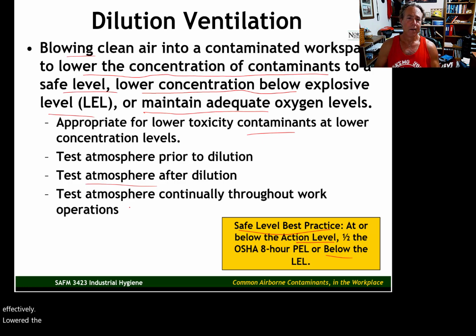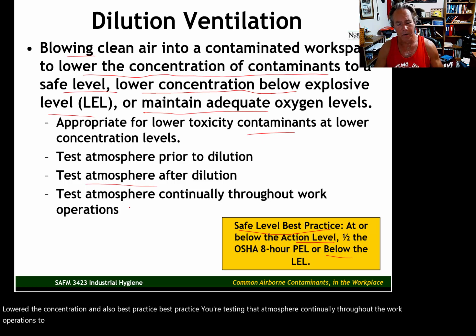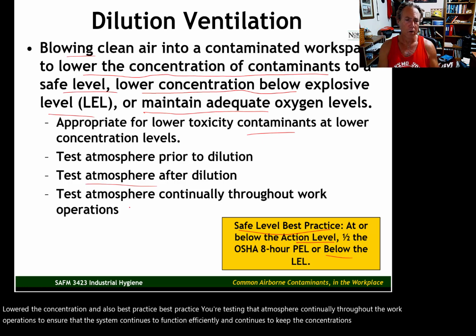And also, best practice, you're testing that atmosphere continually throughout the work operations to ensure that the system continues to function efficiently and continues to keep the concentrations at a safe level for workers.